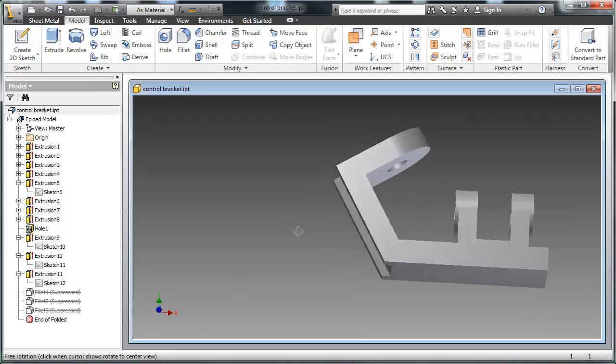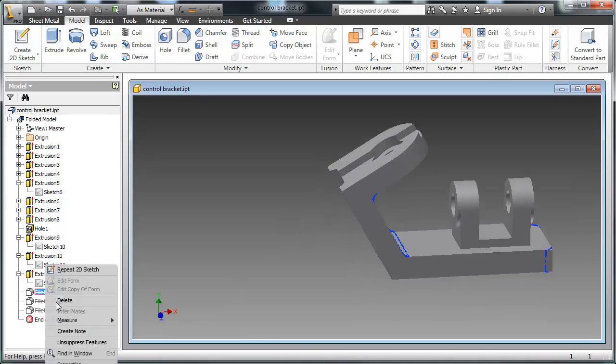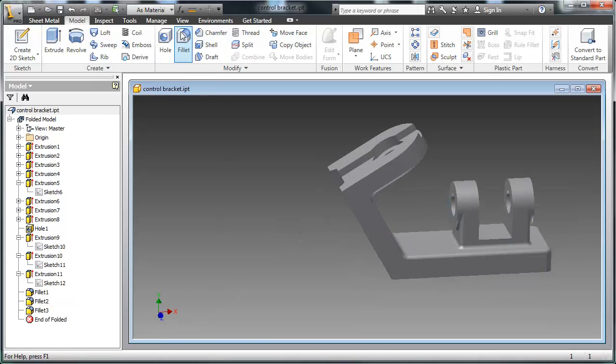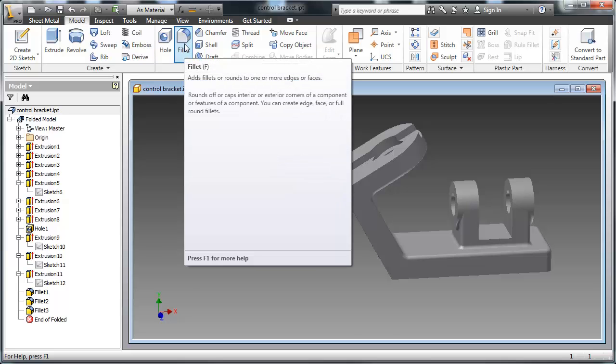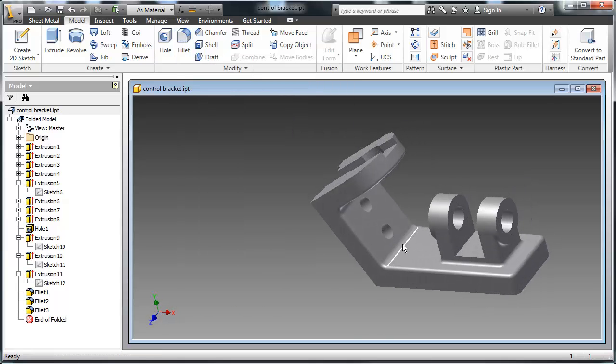those through that part. Our last features here are the fillets, making use of the fillet feature here to add these two different size fillets here. These two edges are 6mm fillets, and then all the others are 3mm fillets. This concludes the Autodesk Inventor interface.